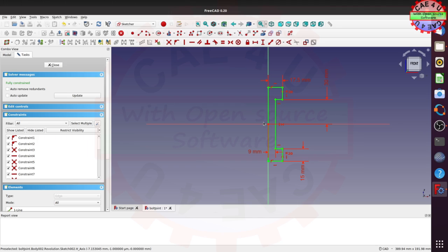So there will be a clearance between the bolt shank and the hole, and it is assumed that the shank does not interact with the flanges, so there won't be any contact pairs created between them. The contact will be created only between the bolt surface and the flange surfaces. Another important observation is that the bolt has been made as an integral part of the shank, which means the thread has enough shear strength to withstand the external load which the joint will experience.